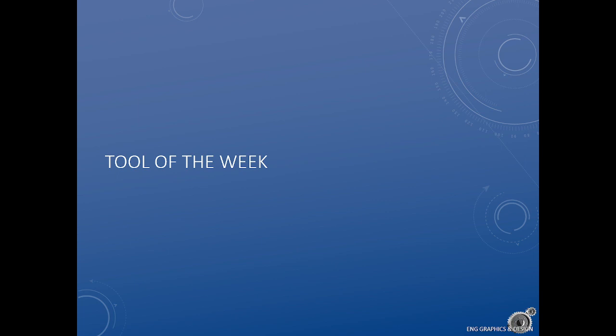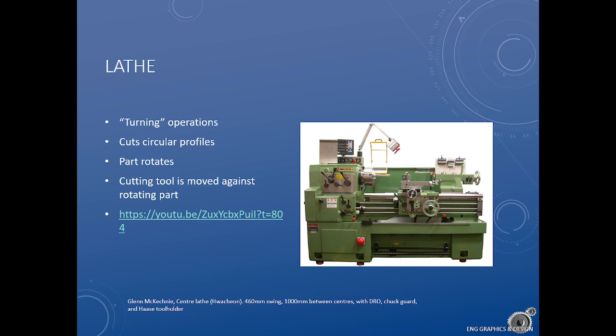So, here's my segue, tool of the week. This week, we're talking about the lathe. Most of you have used a lathe now. It is for what we call turning operations. It's still a cutting tool, still cutting material off of stock. But we're doing it by turning the material and pushing the cutter against it, unlike a milling machine where we spin the cutter and move the material against the cutter. It's sort of doing the whole thing backwards.